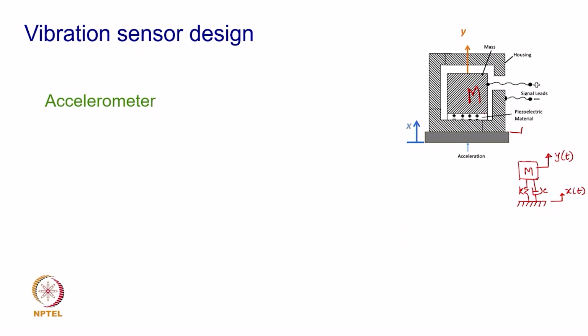Now, when the piezo material is compressed and generates a mechanical strain, the output is a charge which is taken out. What you can notice here are these leads which are connected to the mass as well as to the base. From the base or the housing, one lead is coming out, the other one is through the mass. So, the charge travels from both ends and you collect the charge as an output. Based on the compression in the disc, the charge output is proportional to the mechanical strain in the discs.